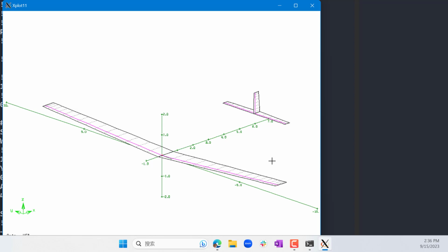The y moment actually is the one you normalize with the chord, because the y moment doesn't have opposite motions on the two wingtips. And x and z moments both are usually normalized by the span, because in x and z moments, the two wingtips are doing opposite things.